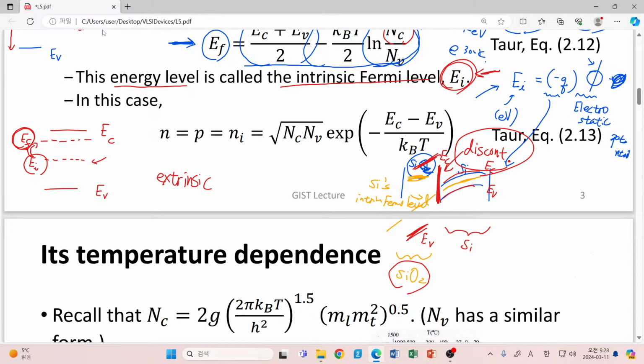Another case, for example: if you have a gallium nitride material, then inside the gallium nitride material you can introduce many different materials based on the gallium nitride material system, introducing, for example, aluminum. Then, depending on the composition, your band gap or band structures can change quite a lot.